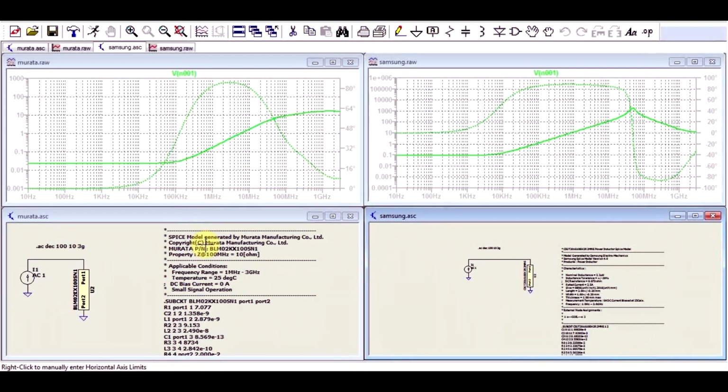an electrical circuit. The power inductor is used to store energy, so it has a very clear inductive behavior with minimal losses, whereas the ferrite is a filter component, and you want this to be as resistive as possible, so the inductance is not as clear. You just have a high impedance as frequency rises.